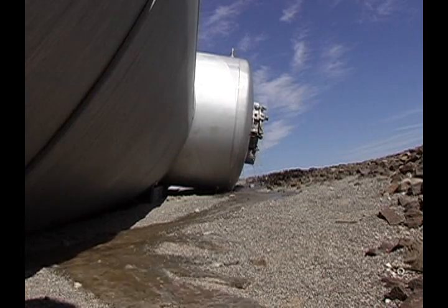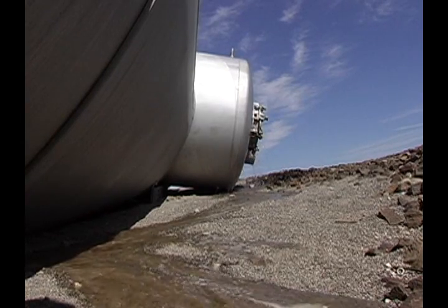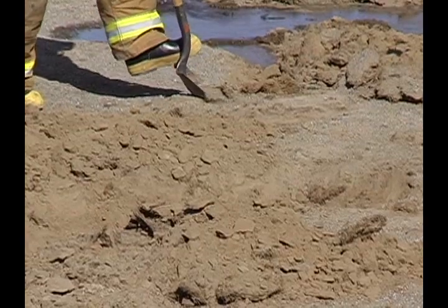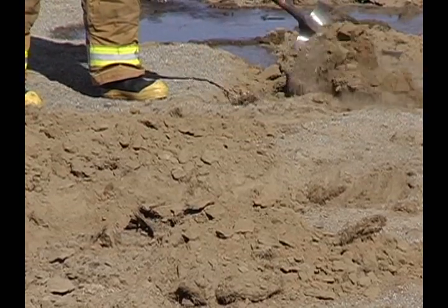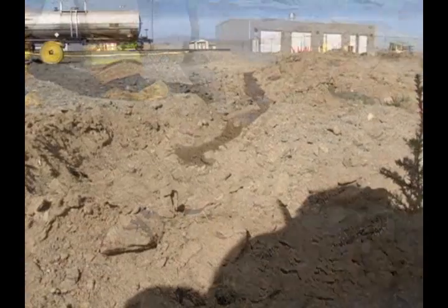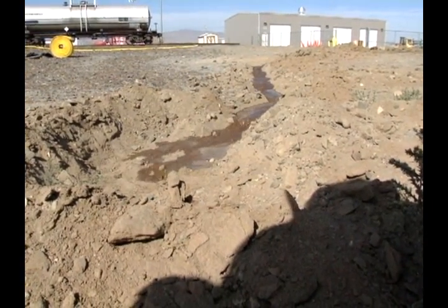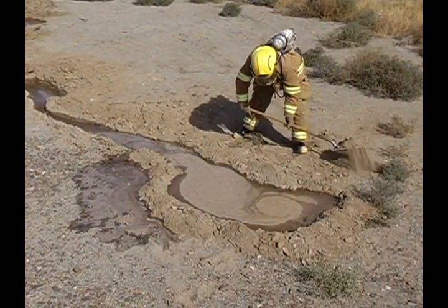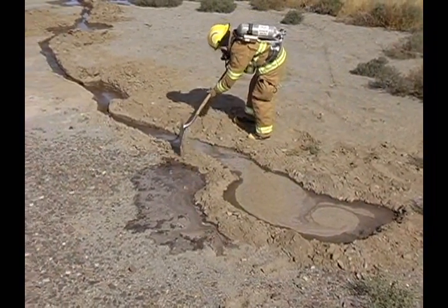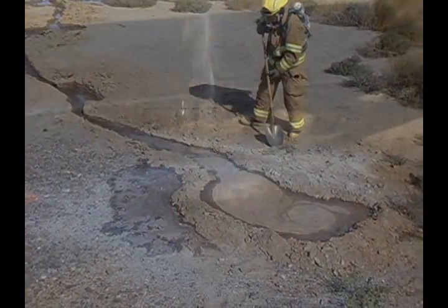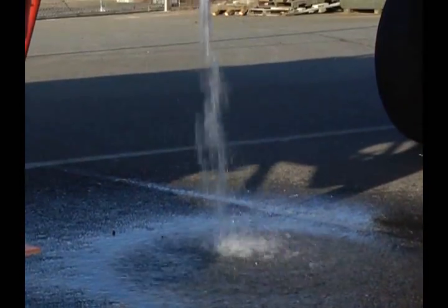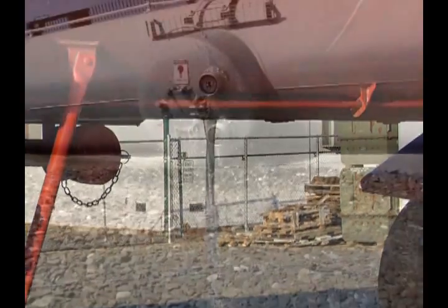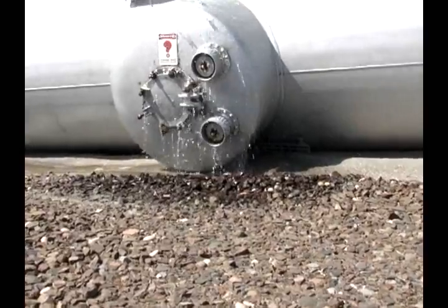The primary objective of hazardous material spill control is to stop the flow of product in order to protect life, property, and the environment from contamination. In general, the product should be confined to the smallest possible area, as close to the source as practical, to make cleanup and removal easier and less expensive. However, flammable liquids should be channeled away from the incident site, all exposures, and potential ignition sources wherever possible.